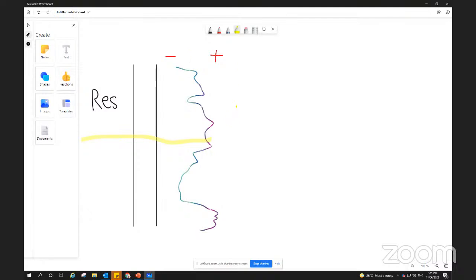Now, when you take the porosity log and you do the upscale inside the 3D model, you need to run the upscale to capture the heterogeneity and the exact behavior of the porosity log. What does it mean? It means you need to put cells in this way.